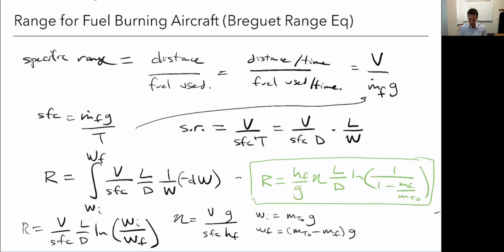You know g. So you're going to have to figure out what a reasonable L over D is, the best we can do. What about efficiency? What's the best total efficiency we can do? What about mass fraction? How much of our airplane could really be just fuel, and how much structure do we need? Try to look at some data on that and see if you can make some assumptions. One hard part is that we generally can't do all of these best at one time, right? If we make L over D really big or make the structure really light, then we can't carry big engines. If it's a really minimal structure, our efficiency is going to be less. So there are going to be some trade-offs, but give that a shot.